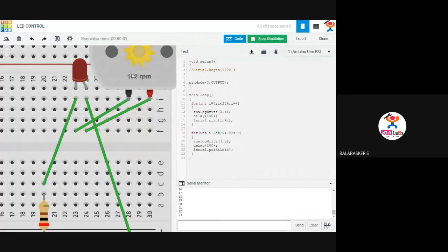See, this will be increased. You can't see any value here because you did not tell the system that you are going to start a communication. So first thing, you have to make sure your board is communicating with the system. So I am saying Serial.begin(9600). So 9600 bits can be transmitted per second.